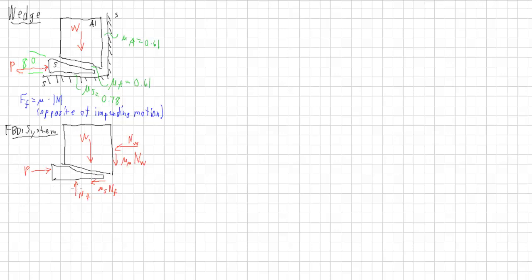I'm going to move on to the free body diagram of one of these 2 blocks. Now if you look at this block, we have an unknown force P and an unknown force N at the floor, and when I get it by itself, we also have frictional forces and normal forces going on right here in between the two. So I'm going to have 3 unknowns there as well.